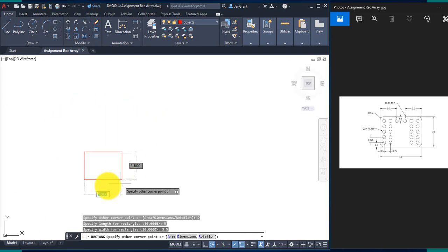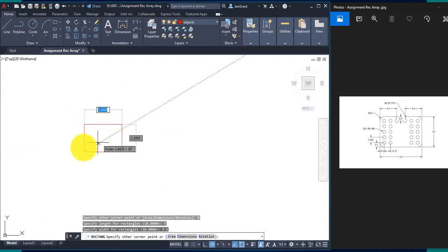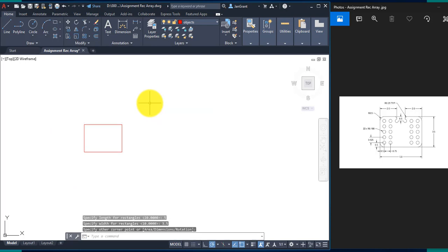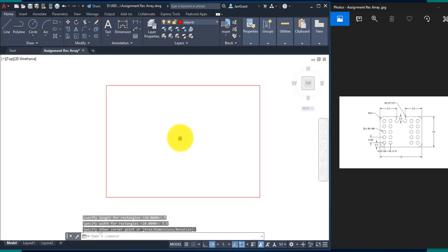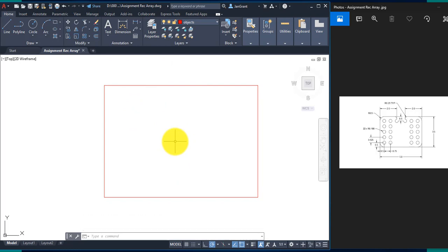Now, you're not done yet because you've just created the dimensions for your rectangle. So we'll pull our mouse up here towards the right and left click. There. Now, if you wanted to go back and draw that as individual lines, you can. Now, because this is a polyline when you draw a rectangle, we're just going to get into this habit, which you don't have to do. With this one, we will because we're going to be building out this piece right here. We're going to explode it.